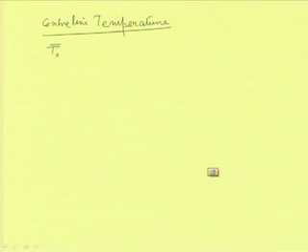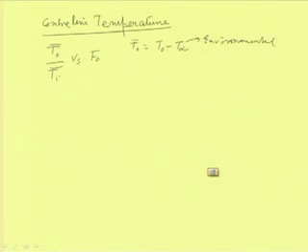So, there is a plot that shows the dimensionless center line temperature, say T0 bar by Ti bar, versus Fourier number. So, T0 bar is equal to T0 minus T infinity. This T infinity is the environmental temperature condition.